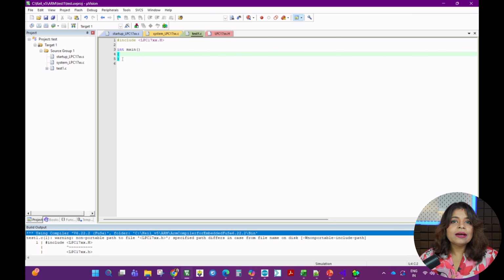Suppose I give MOV A, 100 for the 8051, or for ARM, MOV R0, 100. For MOV R0, 100, there is an opcode associated with it by the LPC1768, that is an NXP device. The processor understands that opcode, that this particular opcode is moving some data to the register. That opcode generation is done by the compiler.